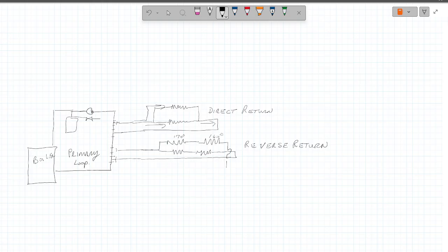This point right here, we're coming back at 160 degree water, because let's say there's a 10 degree drop across this as it goes in. This one will get 170 degree water, but this one takes 160 degree water there. So by the time it comes back here, this one's actually 155 degree water there. So we want to keep this balanced, but as we do that, the temperature is going to change.